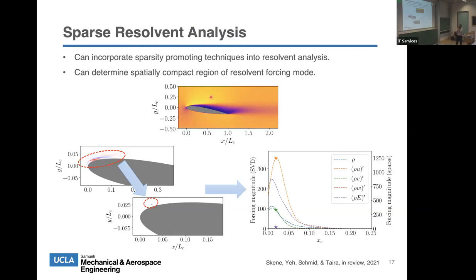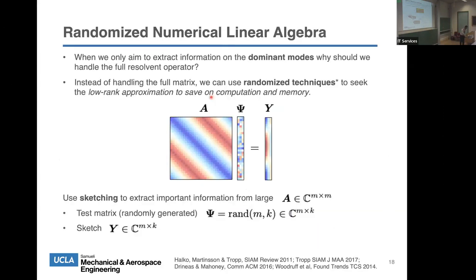And furthermore, our thermoacoustic actuator, that I was saying all these nice things about at the beginning, may not be the best thing to do, because resolvent analysis is saying that I should be using rho u prime and rho v prime as my actuation input, so momentum injection, right? Moreover, because I have rho u prime and rho v prime, the actual value, the amplitude, is now going to tell me which direction I should be blowing. So these techniques are now telling us a lot about how we should be doing flow control. I'm going to talk a little bit about this because I really like this work by our colleagues in applied math, right?